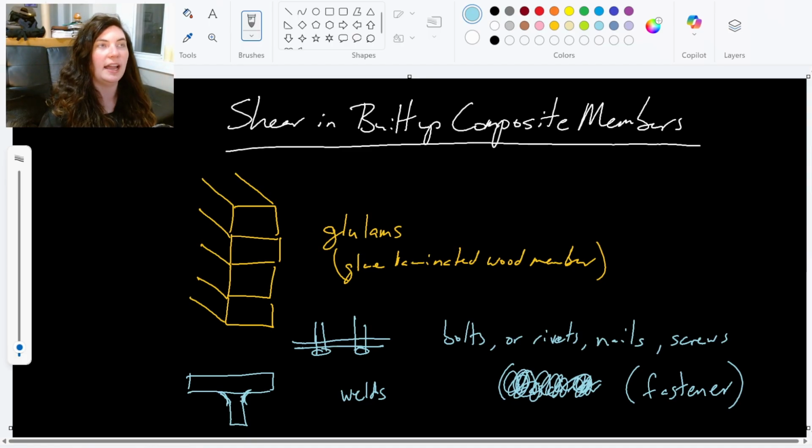So as we're designing these, right, typically the way we think about designing beams is first we want to think about the overall shape, the cross-sectional shape that we want our beam to be in, and what materials we're going to make it out of, right? We've talked a lot about material properties that give you these like stress strain limitations, these moduli of elasticity, all these properties that you can get from different materials, and we can select a cross-sectional shape that meets our function needs, our serviceability needs.